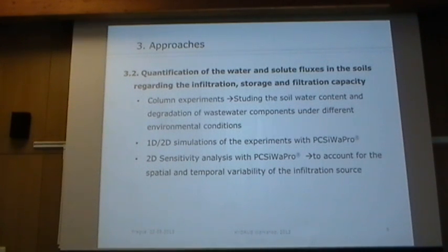So to quantify the water and solid fluxes in the soils, we conduct column experiments in which we study the soil water content and the degradation of the wastewater components under different environmental conditions. And we have simulated the 1D and 2D experiments with our model. We also perform a sensitivity analysis to account for the spatial and temporal variability of the infiltration source.